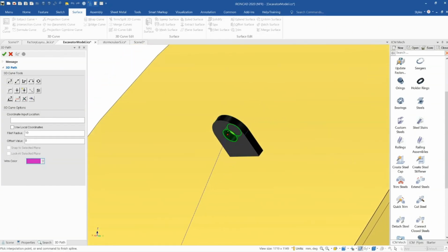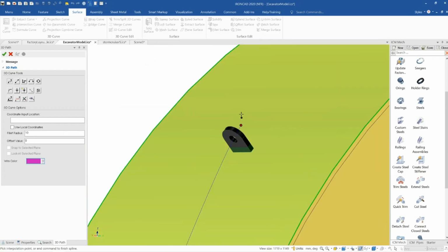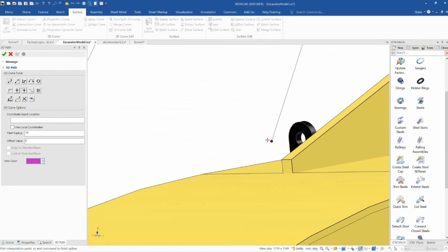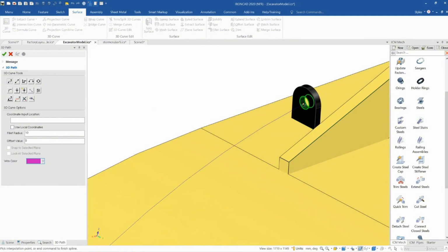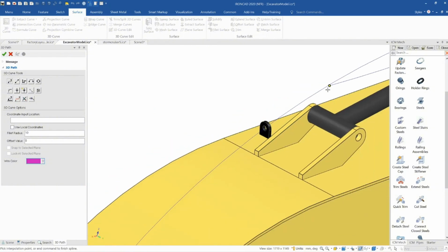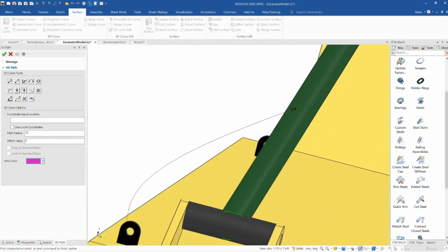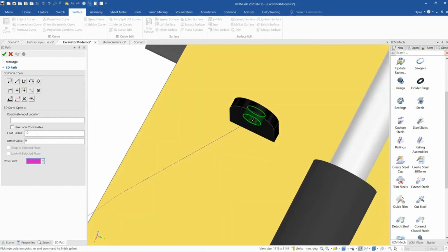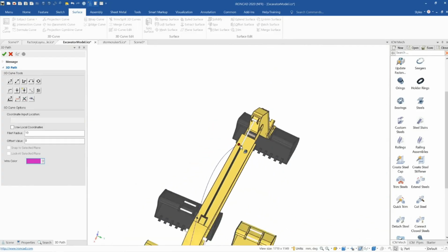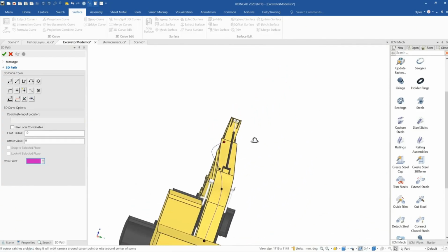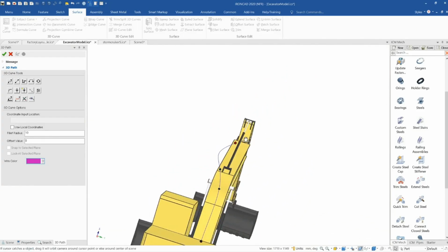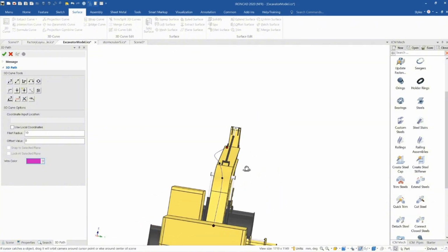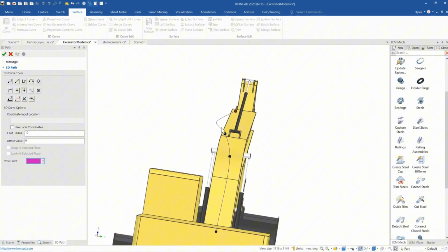So I'm just going to click individual points, just a single point there, and then go ahead and press this single point, something like that, and then let's select this one up here. And then whenever you're ready with the 3D curve, you just hit the escape key to finish it off. And as you can see, it's not really aligning the way we would want it to there. It's a bit kind of off to the side.